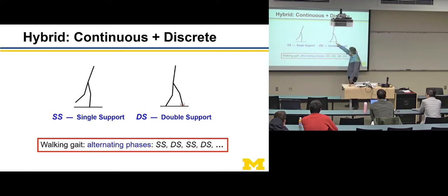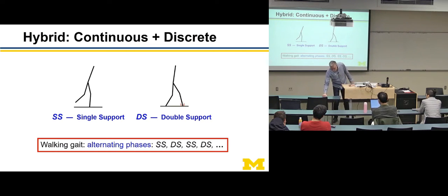The other thing is you can model the impact as a spring damper. That's more accurate. But then what is the spring coefficient and what is the damping coefficient? I don't know. Is it the same for this floor as it is for the carpet? The answer is no. So which one do you use? Well, it depends where you are, but I want to go lots of different places. So usually it turns out best to forget about the spring damper, because you can't figure out the right model parameters, and to use the impulse model.